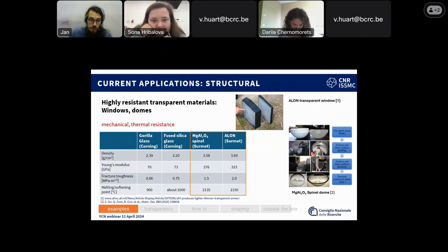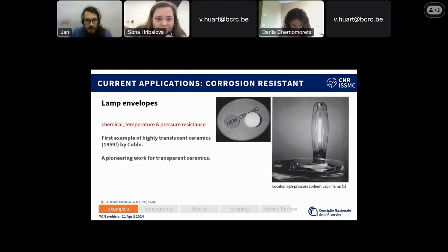Another possibility is to use vacuum sintering, where on the other hand, you apply vacuum from outside, you evacuate the green compact, and therefore you have also less air to deal with from the beginning. And another thing that you could do also is the use of a sintering aid. Most likely you will do a little bit of both.